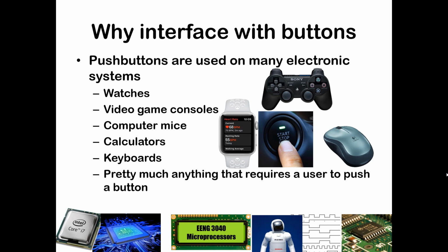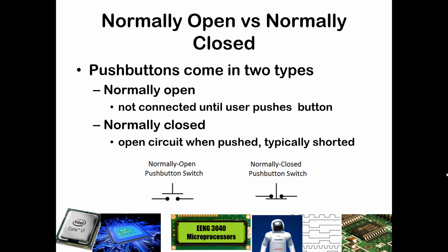So in this lecture, we're going to understand how those buttons are configured and how they can be connected to a microcontroller to determine whether the button is pressed or released. The first thing to understand is that not all buttons are manufactured the same way. Push buttons can be either normally open or normally closed.